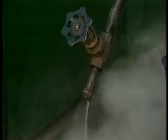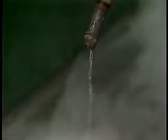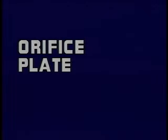Initially, condensate was removed by simply cracking a valve, wasting the hot condensate and some steam as well to the atmosphere. The next step in condensate removal was the application of an orifice plate. These plates were simply discs drilled with a fixed hole or orifice. They were inserted at the steam line drip point or equipment discharge line, draining condensate and venting non-condensables from the steam space. The orifice plate had its problems, though.